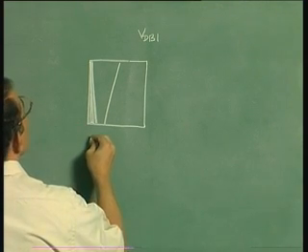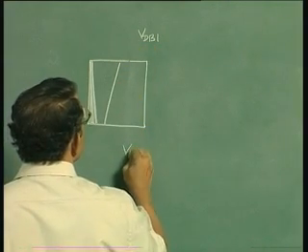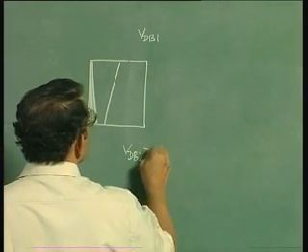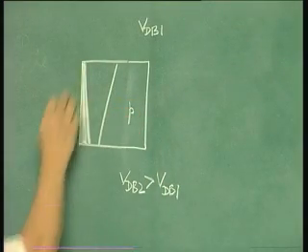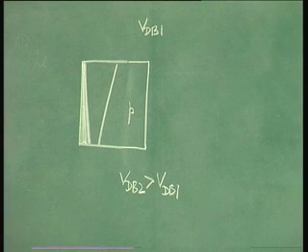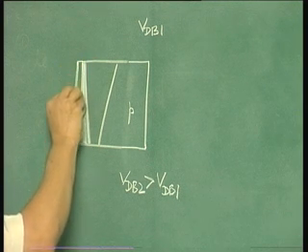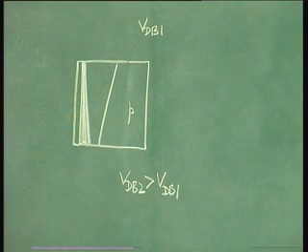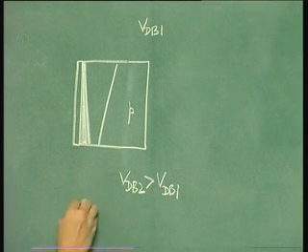Now for another value of VDB, VDB2 greater than VDB1. So this is the p-type substrate. We are not showing source and drain, it is understood this is drain and this is source, and of course you have a gate on this side. So maybe we will just show the insulator. So for VDB2 greater than VDB1, your picture would be as follows.